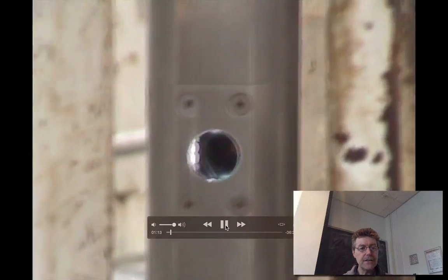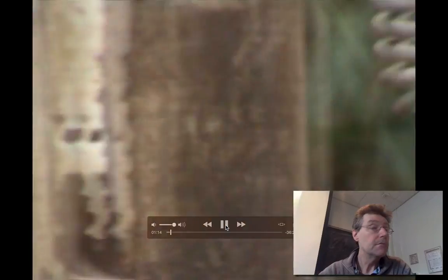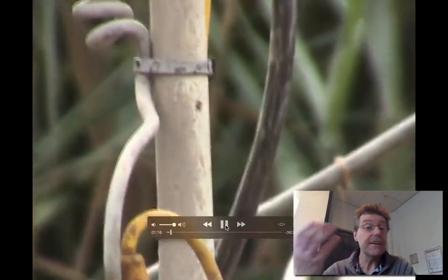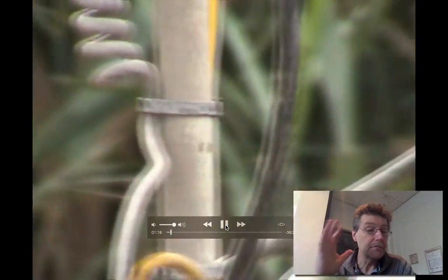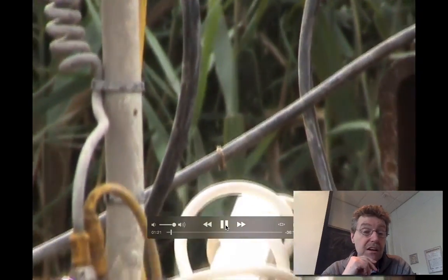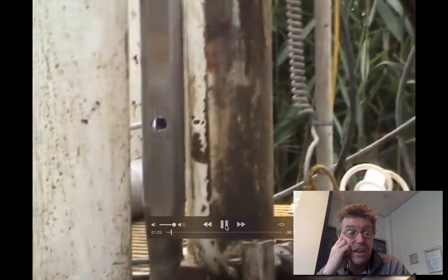And the whole idea here is this is called the vis cone. So this is maybe a meter behind the tip of the cone, but as it goes through the soil, it illuminates the soil to see exactly what it's going past. And so you get a continuous movie of the soil as it comes past this window, and you know whether it's a sand or a clay or a silt or whatever just by looking at it. Or you can see if it has any napl as well as it squeezes past. Really very curious equipment. So this is deploying that piece of equipment at a field site in Delaware.